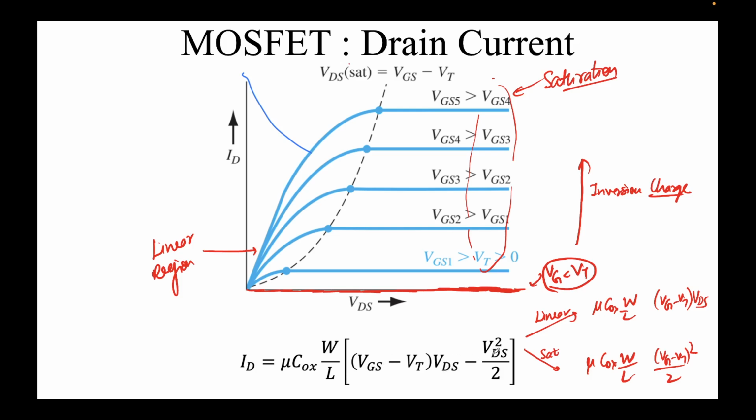and this is also VG minus VT whole square. So that half comes from that part. This is the expression for saturation, this is ID sat. As I was saying in the earlier slides, this expression comes in where we are talking about the temperature dependence of the drain current. So this is the expression that I was talking about in saturation.